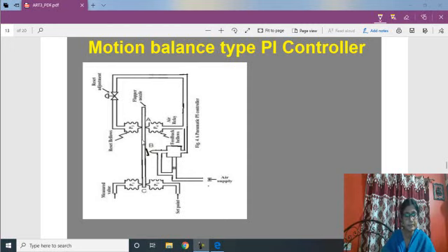This is the motion beam. As you have seen, this is the motion beam and two bellows elements are there. This is for the input signal, the measured signal coming from the process, and this is the set point bellows through which the set or desired signal is sent. The mid portion of this motion beam behaves like a flapper unit in front of the nozzle.